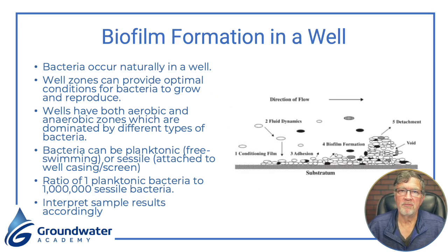All right, biofilm formation in a well. What's important here is it will grow and colonize on the surface of the casing and the screen. And really, when you take a sample of the well water looking at bacteria, it's actually a ratio of 1 planktonic bacteria, that's the free swimming bacteria that will show up in your sample, to 1 million sessile bacteria, that's the bacteria that's actually attached to your well casing.